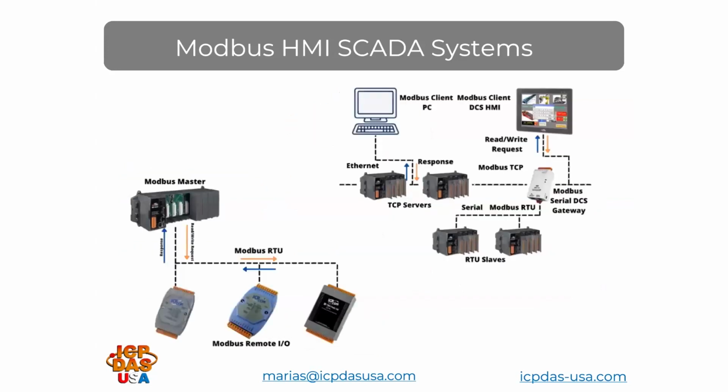Modbus communication protocol allows for request and receive type data transmission between equipment over Ethernet cabling or serial lines like RS-232 or RS-485. It's often used to connect PLCs, PCs running SCADA software, and HMI devices. Control devices send commands to multiple end units that respond and broadcast the requested information. This allows for the status of the system to be displayed on the screen for a quick snapshot of your